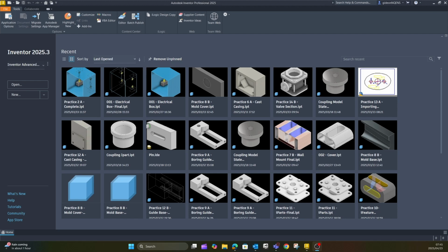Today we're going to have a look at generative design using the shape generator tool in Inventor. Now this allows designers to optimize models by reducing mass while maintaining structural integrity. You can also define properties like material, constraints and loads. The system also generates a shape suggestion that helps you to streamline the design process.